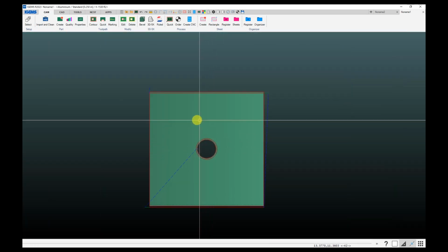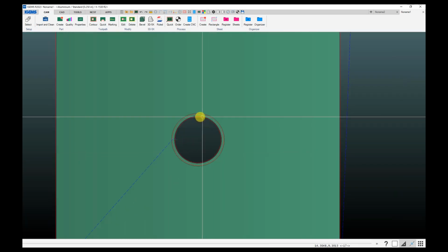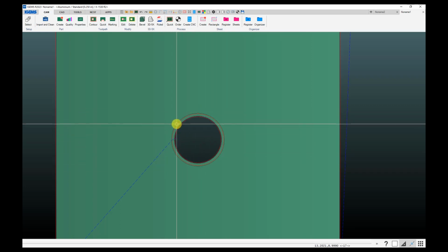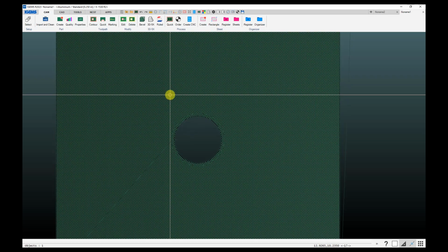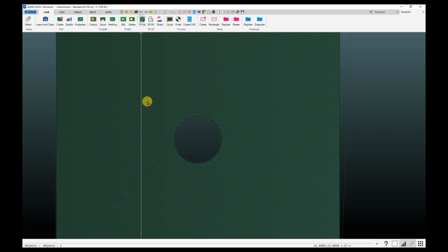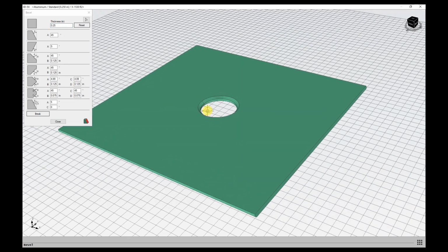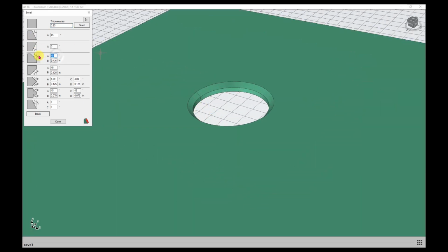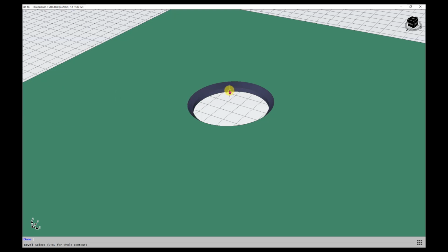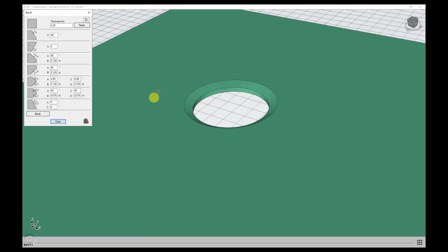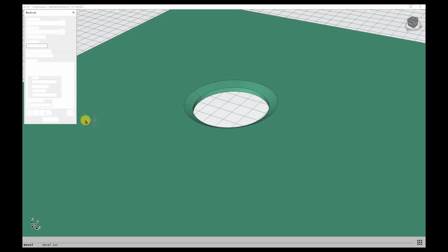If you want to make changes to the geometry, you realize that this is supposed to be maybe a 60-degree angle. We can select it and then click on the bevel button again. Brings us back in there with that part. And so if I want to change that to whatever angle, click on this again, and again hold down my control key, and that changes that angle. And then it also changes the toolpath automatically.